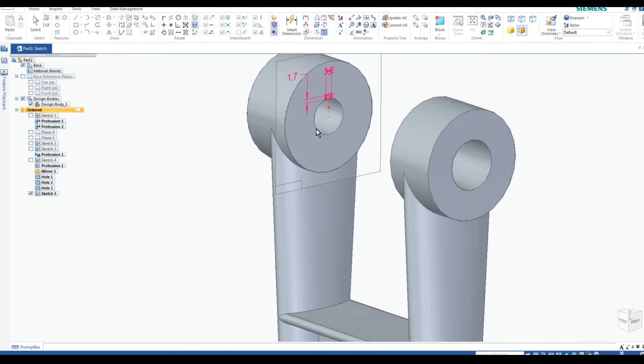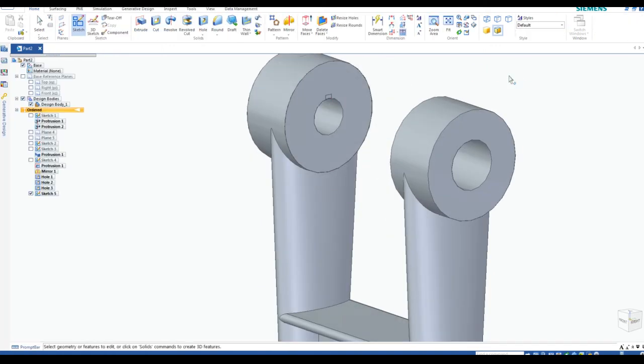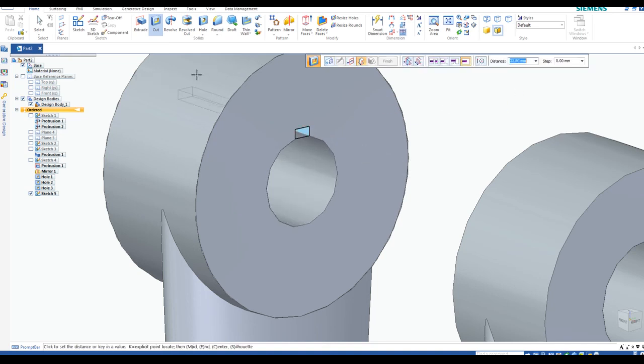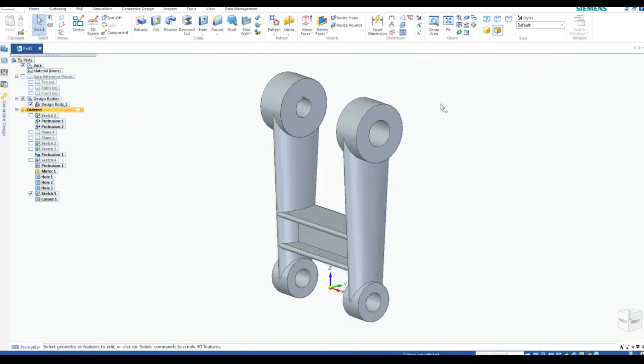Let's close our sketch. Let's finish and cancel. Zoom in, and then we're going to just do a straight, ordinary extrusion cut. So I'm going to take that, let's bring this over here, accept. Oops, I did an extrusion, not a cut. So here's a cut. Same thing, pick, accept, and let's do a through all. There we go, cancel, cancel, and there is our part.